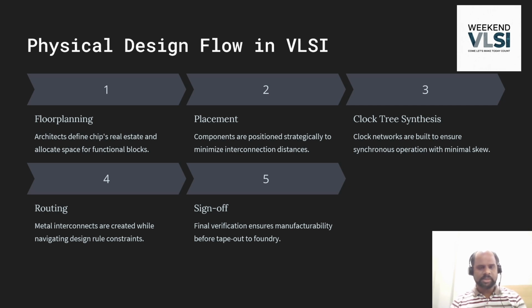Next is sign off. You can ask me one question: once it is routed, will we directly take the GDS and provide it to the foundry? My answer is no, because I have designed it, but now I need to test whether the design will work at the frequency I have designed for, or whether whatever I have implemented is logically and physically right. These are the things we do in sign off, where we sign off to meet the spec.